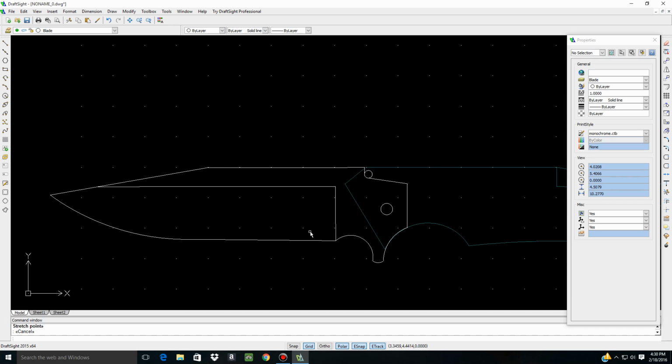Okay, that's looking a little bit better, but I'm going to tell you right now, there is no way that when you go to close the blade, this lock face is going to clear that stop pin. Never going to happen in a million years. As you can see, as soon as we rotate this blade, it's going to rotate this lock face up, it's going to smack the stop pin, and then what? Nothing's going to work. So we definitely need to move the point of rotation forward, right?